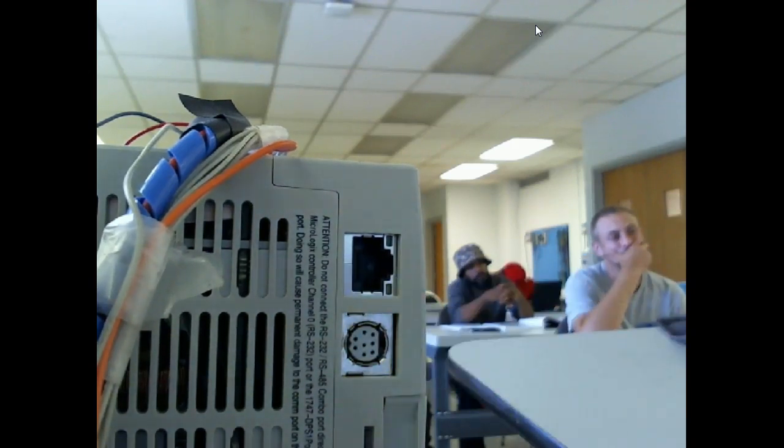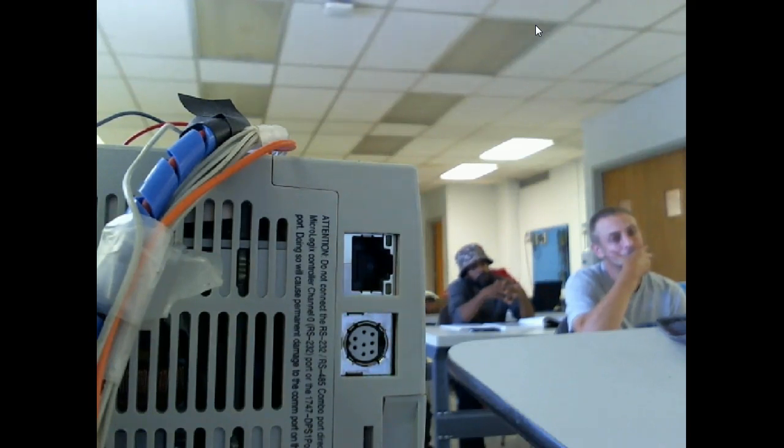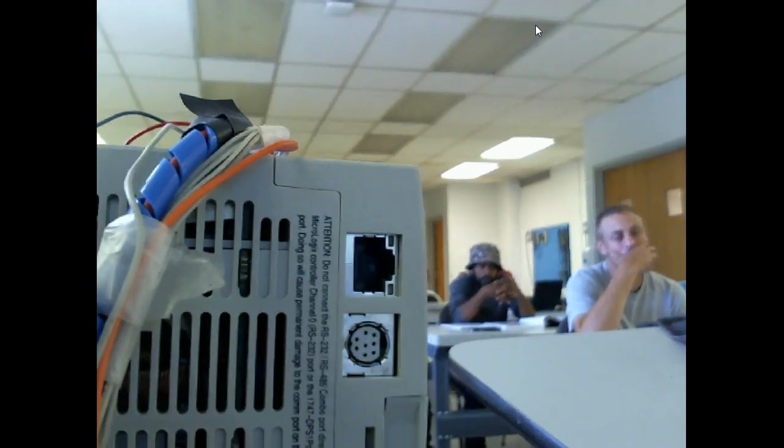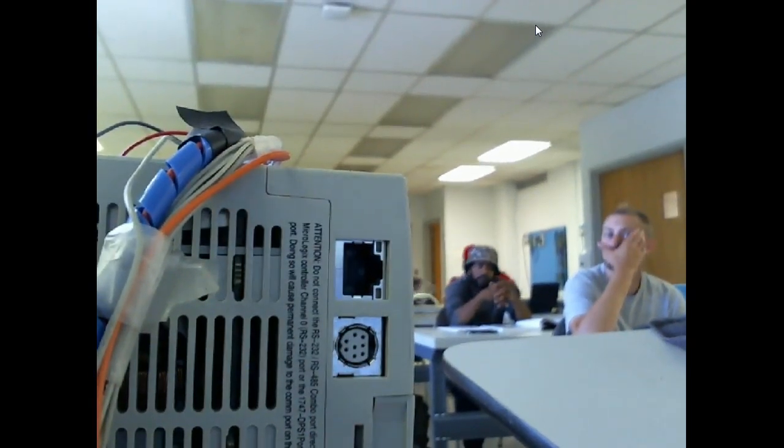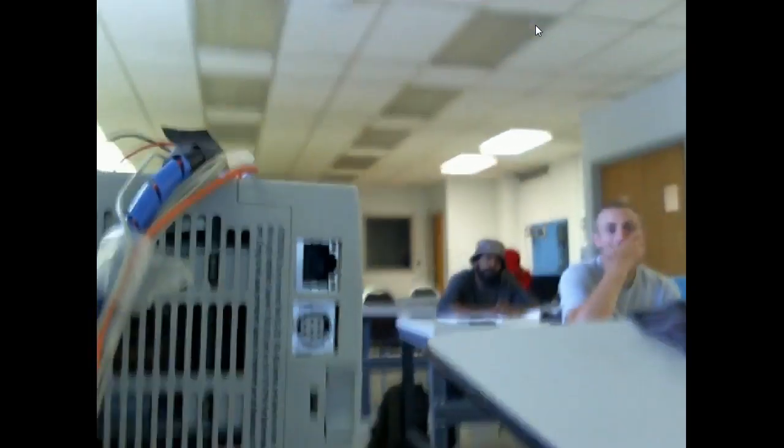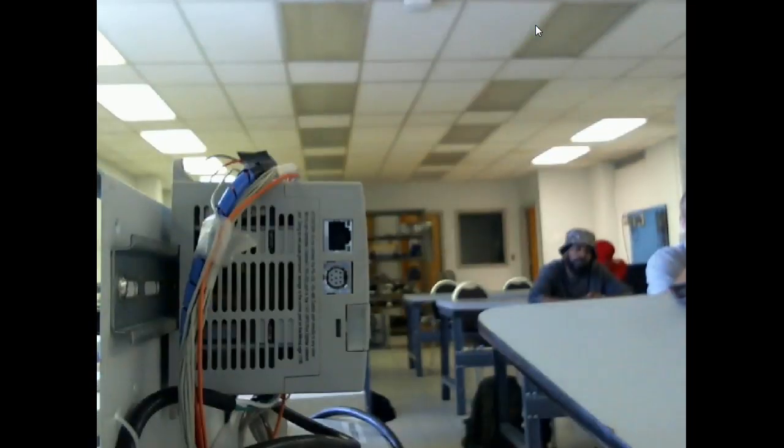Usually it's a lot stronger cable than what I pass out here. This is what we call UTP cable, which stands for unshielded twisted pair. It's a lot cheaper. When you get out in the industry, it's probably going to be what they call shielded twisted pair. They add a metal shield around the cable to help eliminate some of the electromagnetic interference. And it'll be green, by the way. If you ever see these green cables going from PLC to PLC, then that's Profinet. If it's purple, it's going to be Profibus.